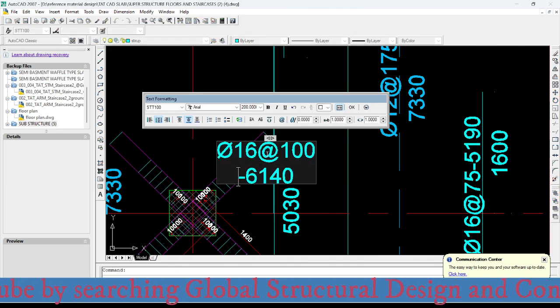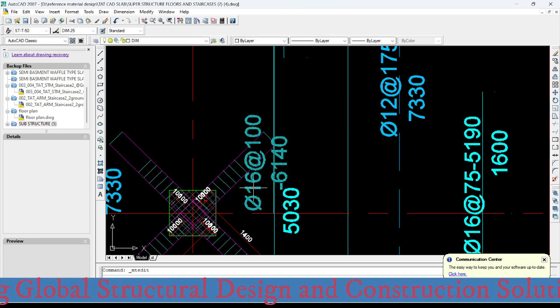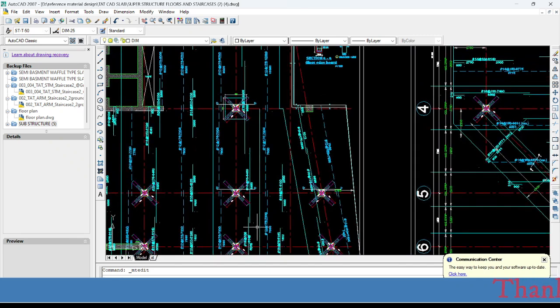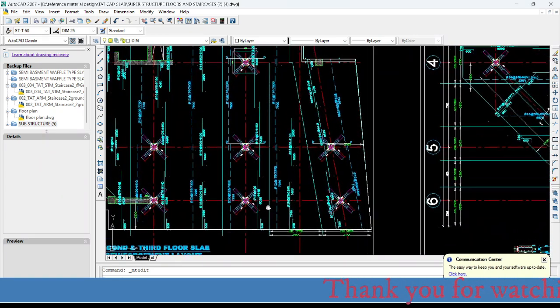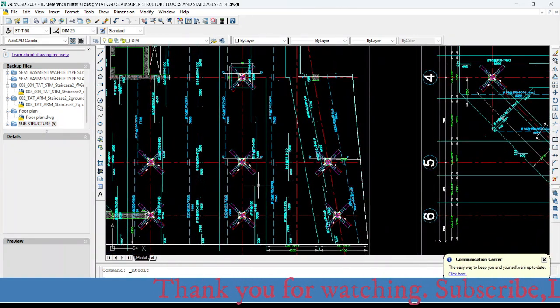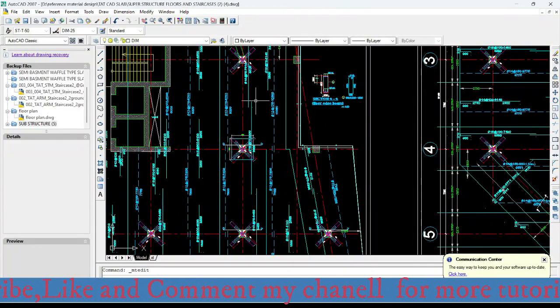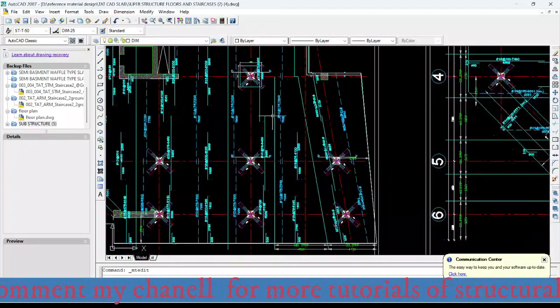So I need to be economical because I need to take the negative reinforcement area at every support in order to be economic. If I take the maximum negative moment of the supports of the strips, I will not be economic. Okay, I have finished detailing the negative reinforcements of the last column strips.